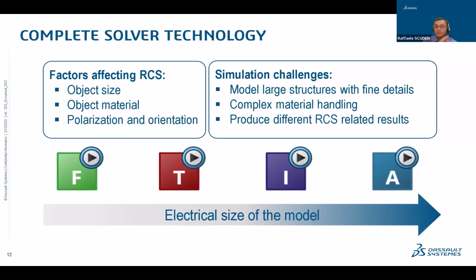As you have seen even today several times, we have different solvers. We have the F solver, which is a finite element method-based solver in the frequency domain. We have the time domain solver, which is actually not a single solver but a family of two different methods, FIT and TLM. Then we have the integral solver, which is a BEM method, and then we have the asymptotic solver when the model becomes really big compared with lambda, or when the frequency becomes very, very high.